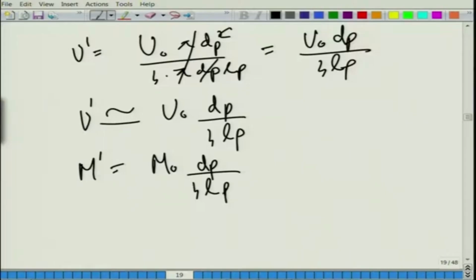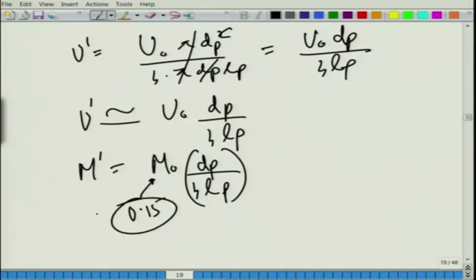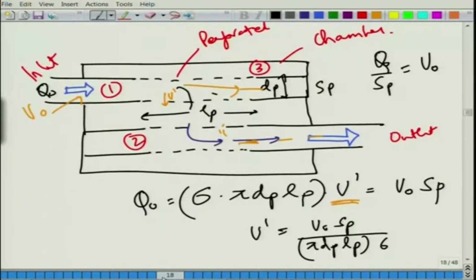Generally the diameter of the pipe is pretty small, about 40 mm, 50 mm for automotive mufflers, and LP is the length of the perforated pipe, which is usually more than the diameter. So again this quantity is divided by 4. And the Mach number, the maximum value is about 0.15 or something like that. The point is that the bias Mach number will be even smaller.